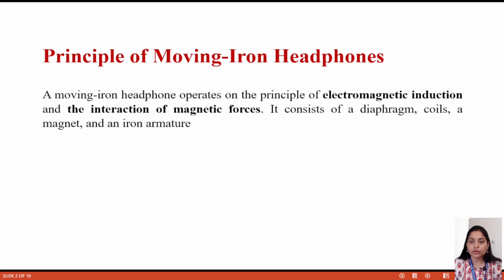Now we will start the next part of this video. Here we will describe the moving iron headphone and also the electrostatic headphone. So let's start with the moving iron headphone principle. What is the principle? The basic principle is the same as other headphones, electromagnetic induction and the interaction of magnetic forces, and the basic construction is also the same: diaphragm, coil, magnet, and also iron armature.